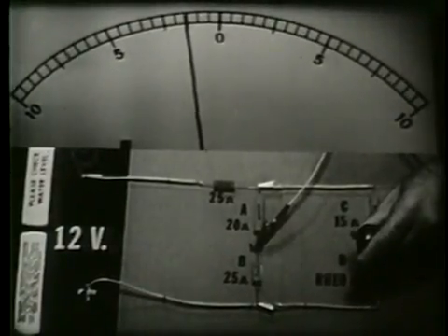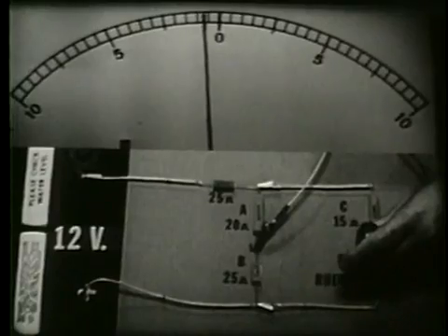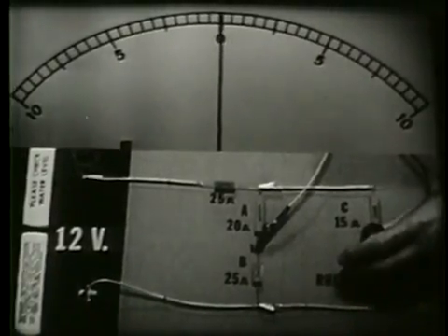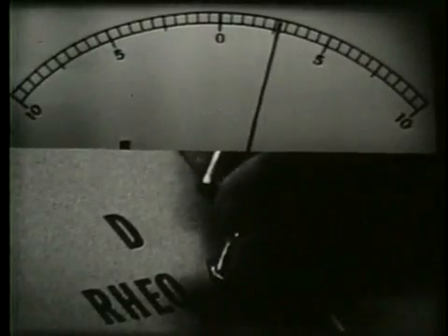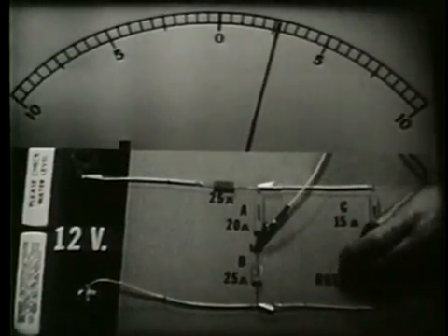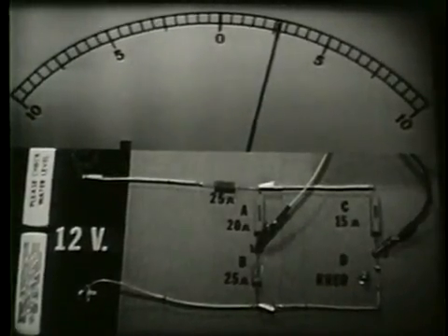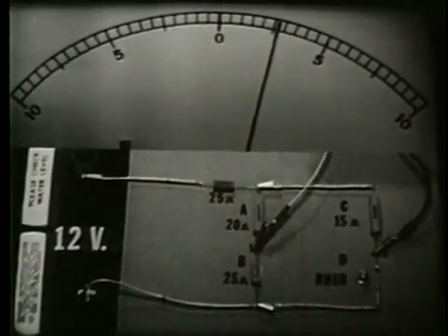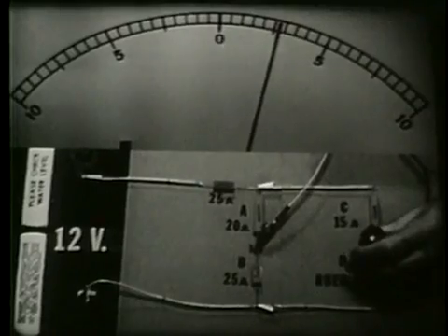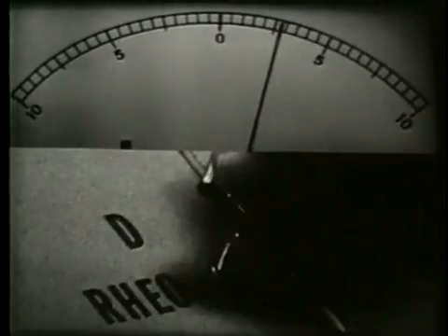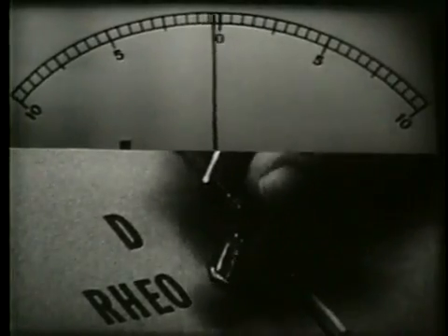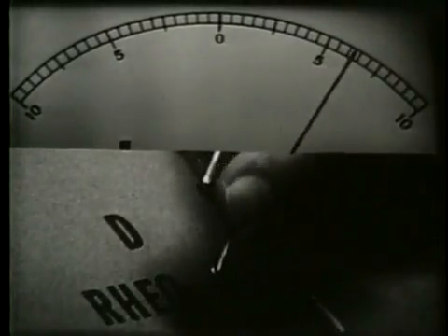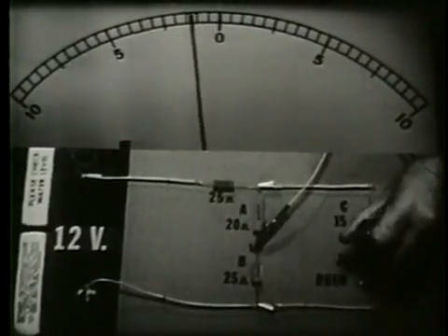By decreasing D, we can bring the circuit back to balance and unbalance it in the opposite direction. Now, point 2 is more positive than point 1, and current flows from left to right. Notice that with a single control, we can cause current through the meter in either direction, and we can vary the quantity of current.